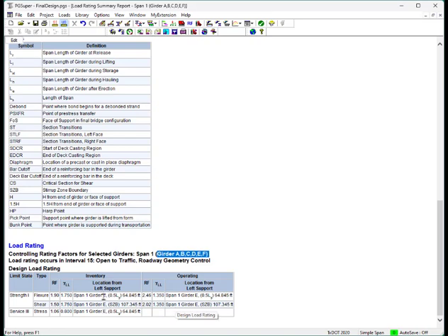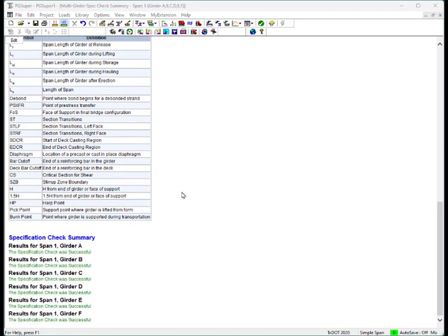One thing interesting here is the load rating controlled for girder E. This isn't a girder that we used for our initial design, and this probably was the controlling girder. I guess it is smart to select all girders at the beginning for design to find out which girder controls. I also encourage you to run a secondary software program or hand calcs to check your design.